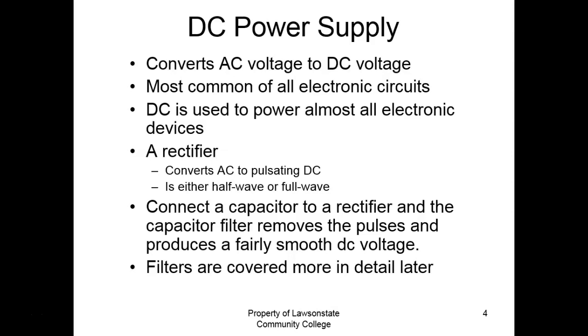So it's got an electronic circuit in it. If I put a load across it, it's going to try to maintain that output voltage with the load, as long as you don't exceed the limit. This one over here is rated at 1 amp. If I try to get 1 amp out of that power supply, then regulation is no longer guaranteed. The output voltage will literally start dropping down. The 5 volt supply is a 5 amp supply. I'm sorry, this is a 3 amp supply.